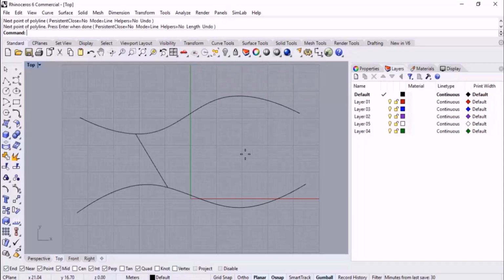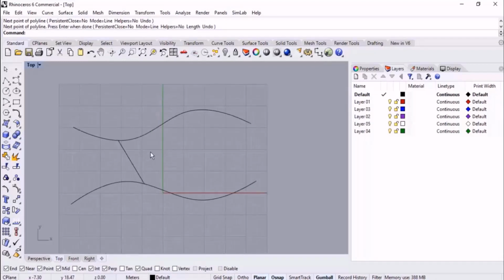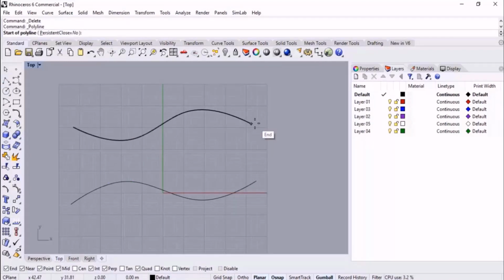All in all, we can use these invisible snaps that can be made visible by holding down the shift button. But let us have a review on the snaps. For example, end, the end point, and the near, it gives us a point on the line or curve. Point, if you got a point in the scene, it gives you the point, midpoint, I told you before. And the center and the intersection.